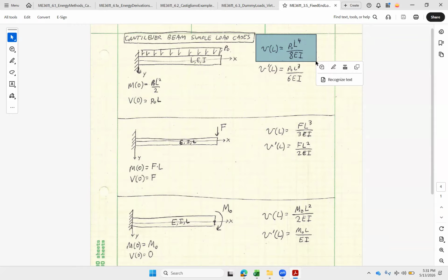It's just a nomenclature. The little script V is what's often used in integral beam mechanics, where you have a deflection of x all the way across. In Castigliano's theorem, we're talking about deflection at a given spot, at some arbitrary spot, wherever the load is. So we usually just use a general delta for that one. But they don't mean anything different. They're just displacement. Little v is always in the transverse direction, and our delta is in whatever direction the load is pointed. So it's just more of a general description.